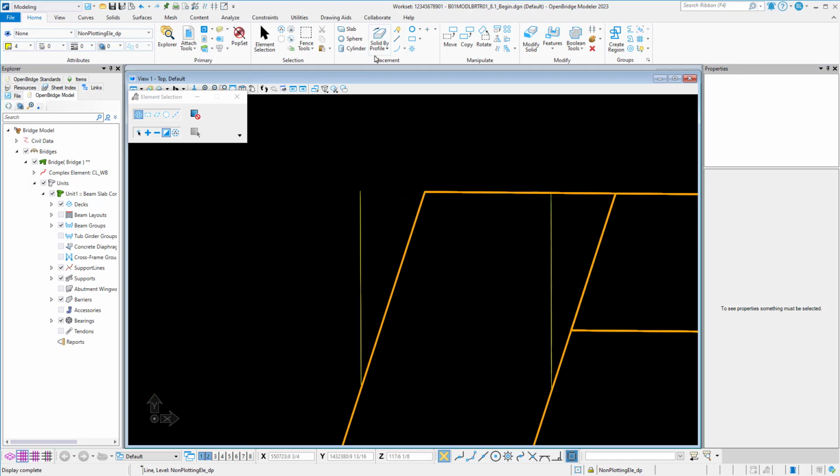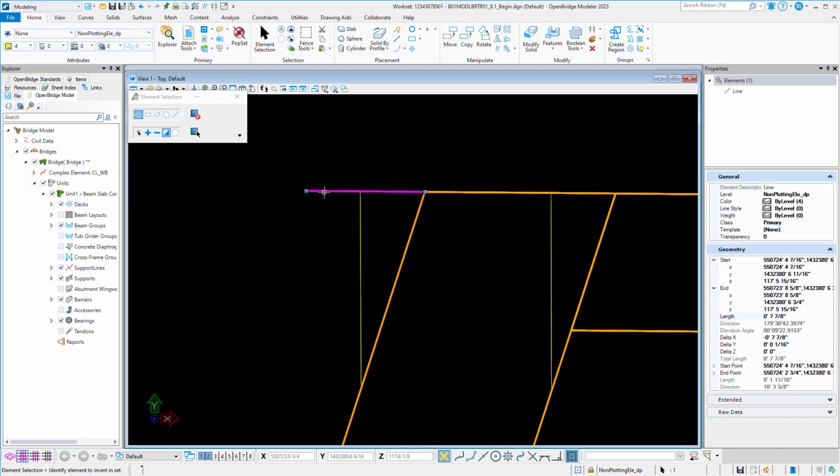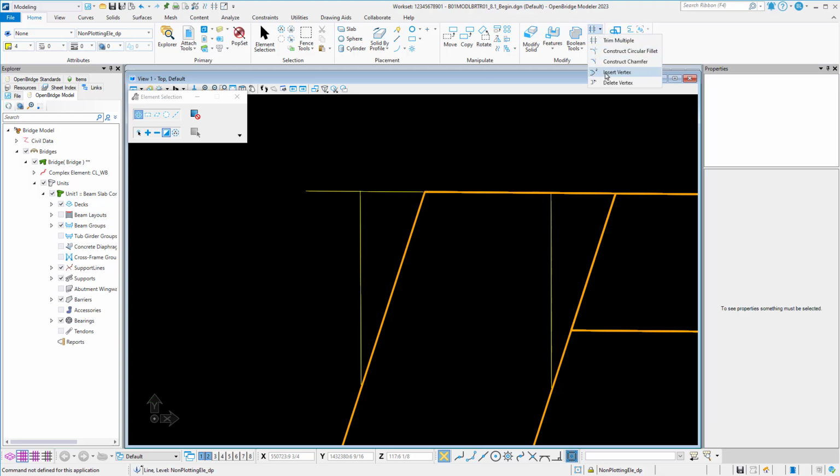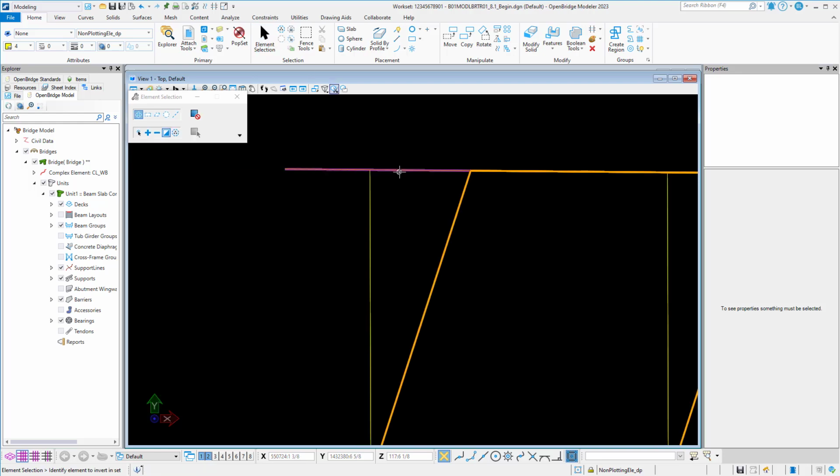I'm taking another step here to confirm that the newly created line at the back face of the back wall and the gutter line truly does go to the end of the end vent as I intended to. To do that, I will create a smart line going along the end of the end vent, and I will trim the created line before from the back face of the back wall and the gutter line to match that new extent.